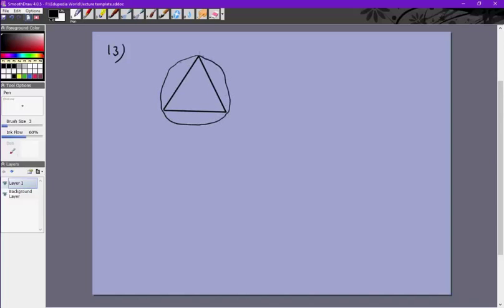So this is our disc of radius r and mass m, and 3 forces are acting along an equilateral triangle like this. So the 3 forces will have the same torque by symmetry. We just need to calculate any one torque and we can get all 3. So we need this distance first, right? Because this will tell us what the torque is. This is 90 degrees. If this total is 60 degrees, this is 30 degrees. So this distance, let's call it small r, is equal to r sine 30, which is r by 2.